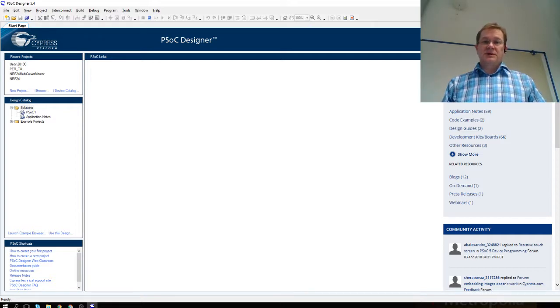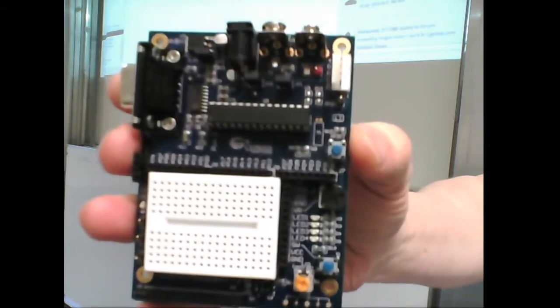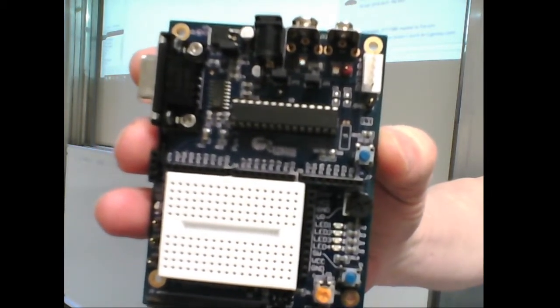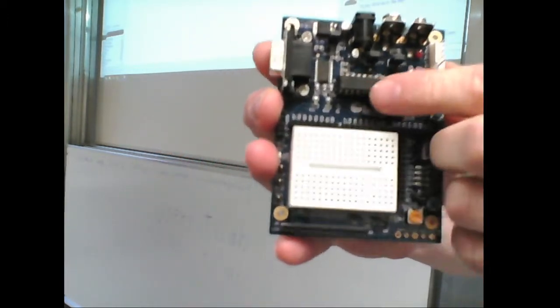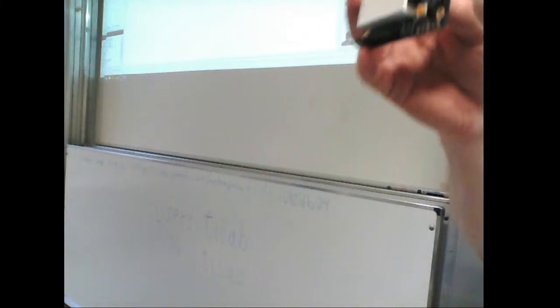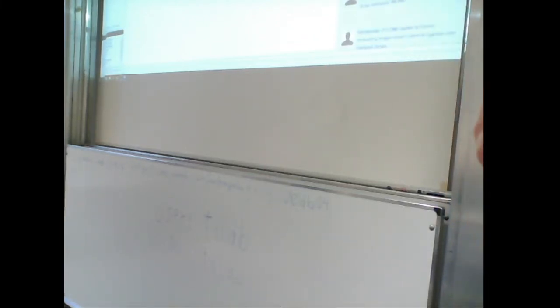Just a moment. So looking at that board, it's either 27 something, so you're looking at this chip here. That's the processor. And in mine, there is a CY8C27443. If it's different, then you probably need to change it.